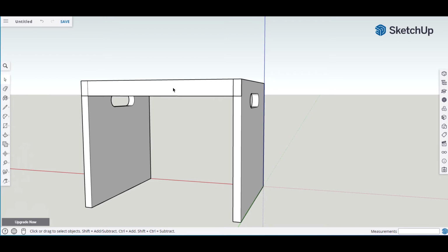So I'm going to go ahead and click this. Now I clicked it 3 times to select the whole side. All right. So now we're going to have to, again, create this 1/2 inch thick. We're going to hit P for push pull, select again, and then just pull the mouse towards you, and you can see you get some depth. So we want a 1/2 inch. So we're going to type in 0.5, boom, gives you 1/2 inch, hit space bar.